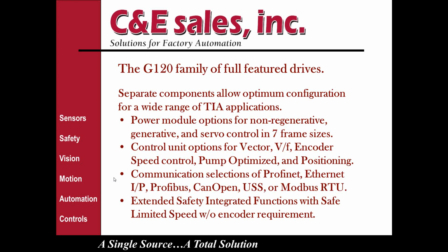So the communications is a big plus on the G120 drives. With that communications, we can do total control across the network using Profi Drive, which is an agreed upon set of protocols and messages that are set up in Siemens PLCs to talk and control with Siemens drives.